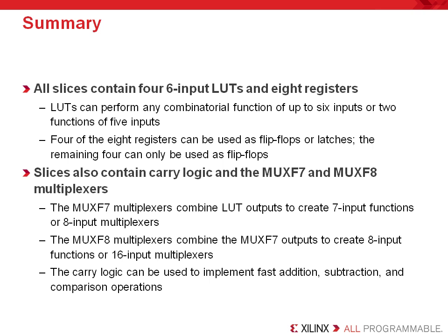The carry logic can be used to implement fast addition, subtraction, and comparison functions as well as other arithmetic operations. And in the end, the reason it's so fast is, of course, because it has dedicated routing resources as well as dedicated logic that are optimized for arithmetic operations.